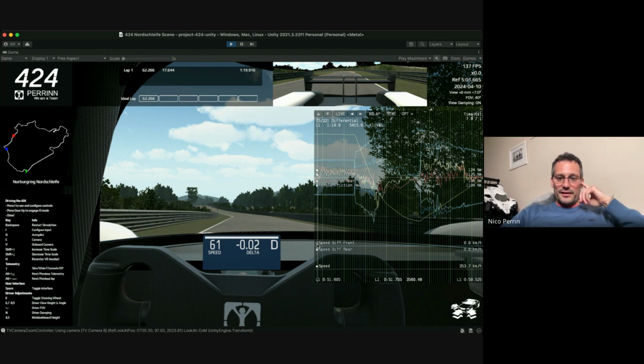The other channels are telling you the torque that effectively goes across the diff. So I talked about the speed difference left to right. This is the torque difference left to right. As you enter the corner, there is a bigger and bigger torque difference because you're starting to steer, and one tire is more loaded than the other one. So one wheel is having more reaction torque through the drive shaft than the other one.